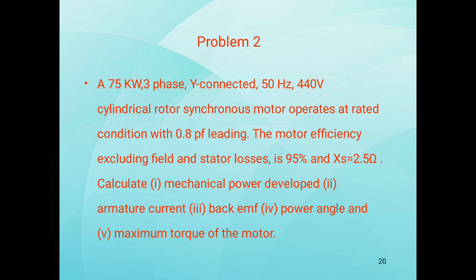Here now problem 2. So read it once again. The 75 kilowatts three-phase Y connected 50 Hz 440 volts cylindrical rotor synchronous motor operates at rated conditions with 0.8 power factor leading. The motor efficiency, excluding field and stator losses, is 95%.